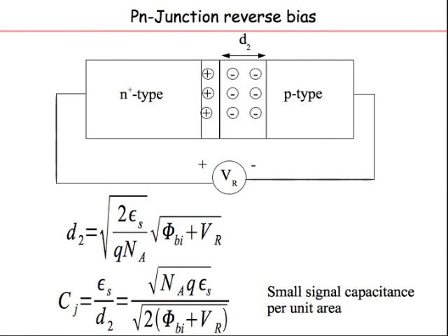If you recall from the previous lecture, for the MOSFET, there is a source drain region, which is either n plus or p plus, depending on the transistor, and that along with the substrate forms a diode. We would like to keep all diodes reverse biased. We don't want to forward bias any of the diodes in CMOS digital circuit design. Okay. So that is basically the way we use diodes.